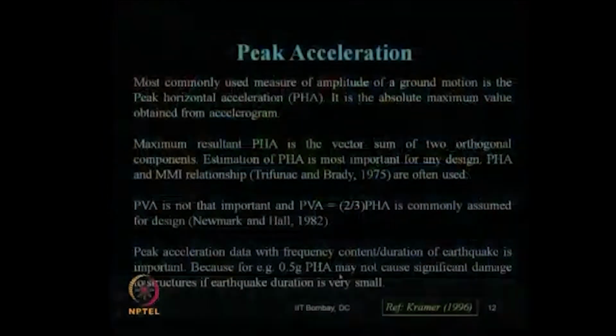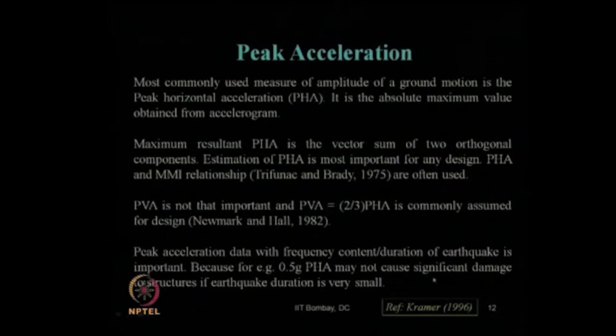But even if the magnitude is small, if we continue it for a longer period, then obviously it will pain a lot. So, it depends on how much response time you are giving along with the amplitude. That is why it is not necessarily true that 0.5 g PHA will cause large damage to your structure if the earthquake duration is very small.